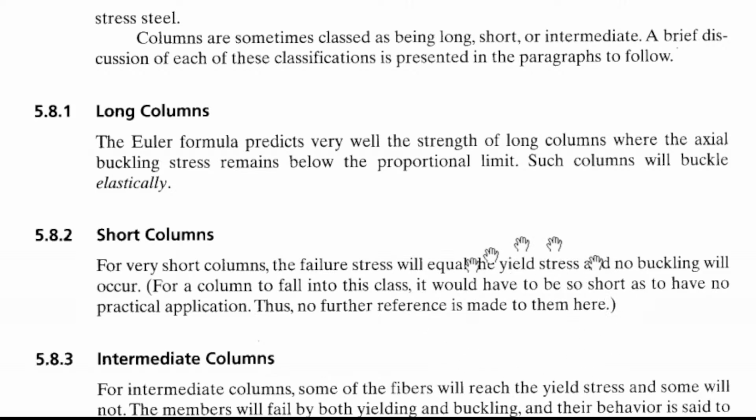So it is almost like a pedestal, with no practical application. Pedestals in reinforced concrete have a very wide area of application. But when you are talking of steel, there is no reason for you to have a very short steel column.